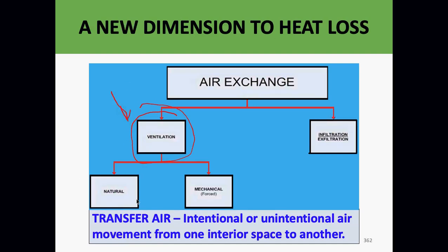We use two ways to ventilate, natural or mechanical. Natural means we have a dryer vent looking thing down at the bottom of the house, and an exhaust up at the top of the house. It doesn't have to be motorized. The cool air will come in at the bottom and leave through the top. That's natural ventilation. Other times of the year, when it's cold outside, cold air comes in, drops, and leaves at the bottom.